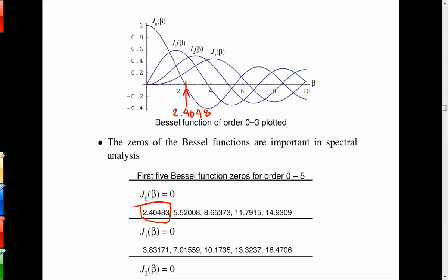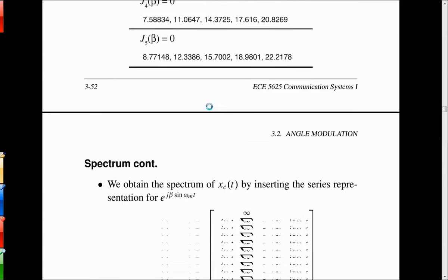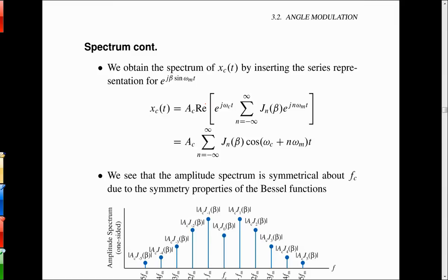This happens to be something that you do in the lab just as an experiment to verify that you understand sinusoidal FM. When you put the Bessel function coefficients back inside, in other words, I modified the notes slightly today because I felt like that was missing. We expanded that e to the j beta sine omega m t into the Fourier series, and that became this representation here.